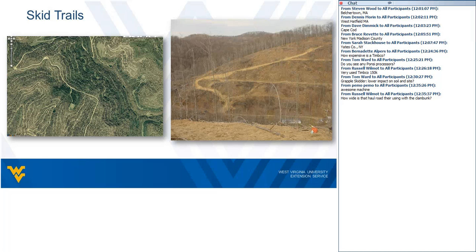If you look at the one on the right, that's probably closer to 65 to 75% slopes. So in order to get that equipment to work on that area, they have to construct skid roads that follow the contours and allow it to work on relatively flat ground, even though up and down from that skid road, where it's pulling the logs from, are significantly steeper.